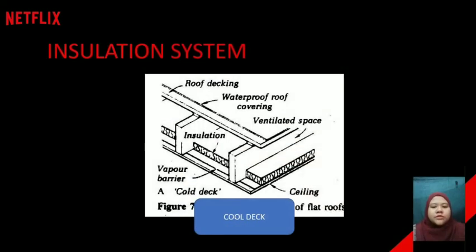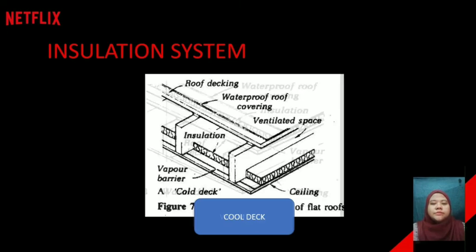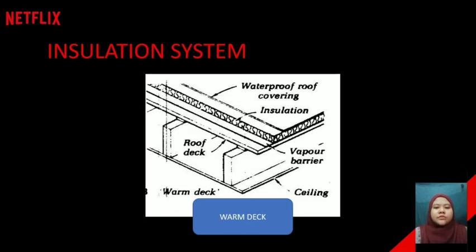For roof design, usually leave a 50 mm gap between the insulation and the roof deck. This allows air to circulate, however, it also allows cool air to enter. Next is warm roof. It is designed to keep the entire roof warm. It is because the insulation is laid over the top of the roof deck, on top of the vapor control layer, and underneath the roof covering.